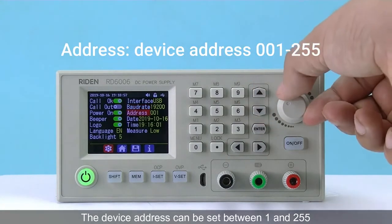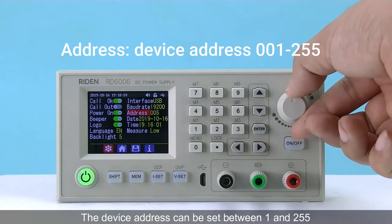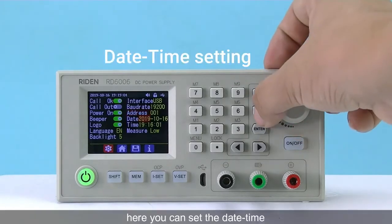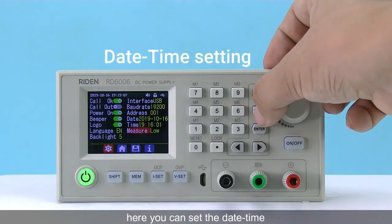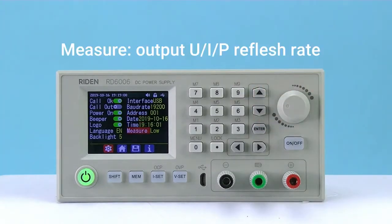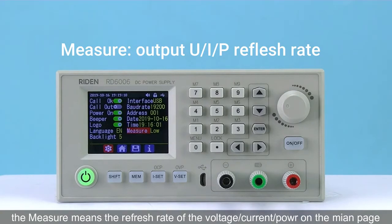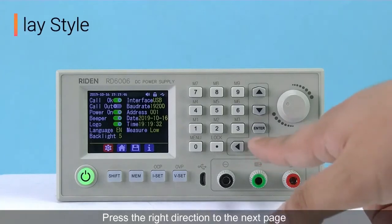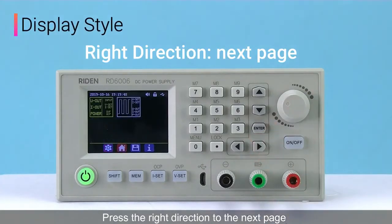The device address can be set between 1 and 255. Here you can set the date and time. The measure means the refresh rate of the voltage, current, power on the main page. Press the right direction to the next page.